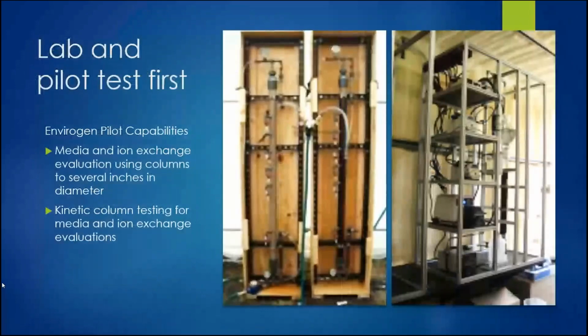If this is a brand new installation, it is highly advised to conduct lab and/or pilot testing before moving forward. During this testing, the optimum media choice can be identified, removal expectations can be set, and the regeneration method determined. Envirogen has lab and pilot capabilities in our Memphis facility.